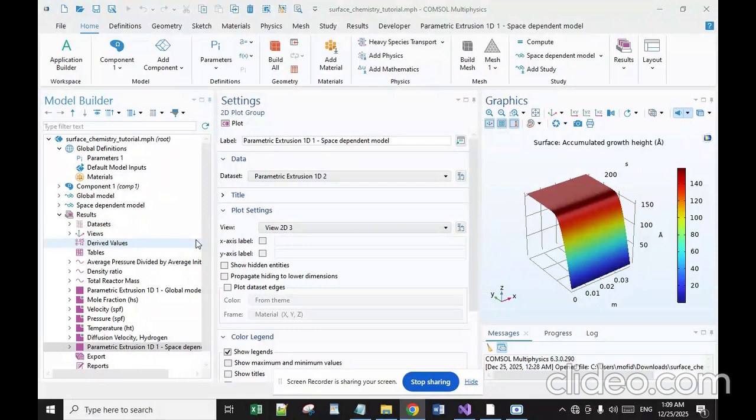Initially the closed container is full of 99.9% silane and 0.1% hydrogen measured by molar content. A surface reaction begins to happen on the wafer, which consumes the silane, releases hydrogen into the domain, alters the composition of the adsorbed species on the wafer surface, and deposits bulk silicon.